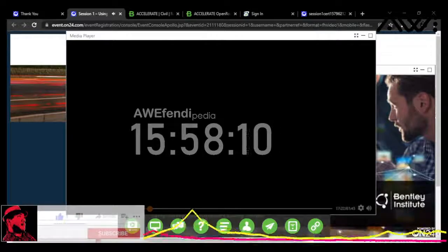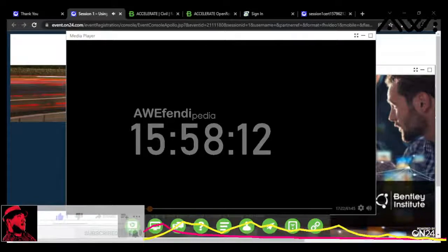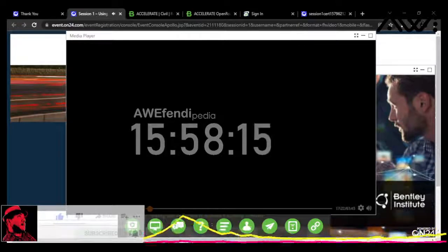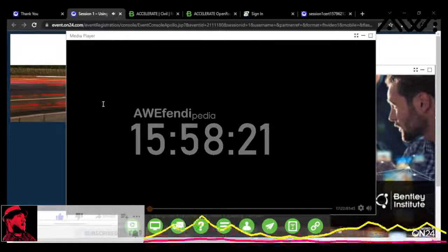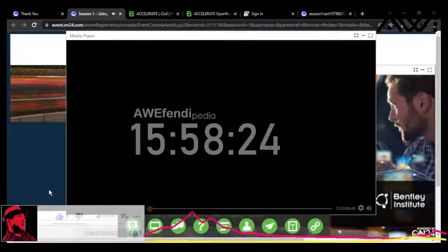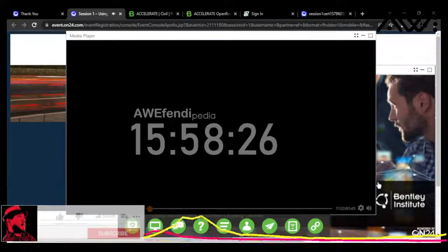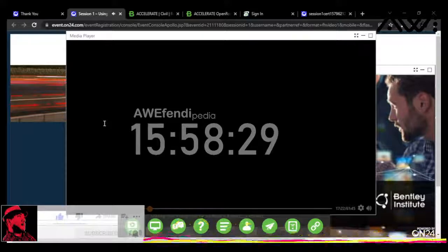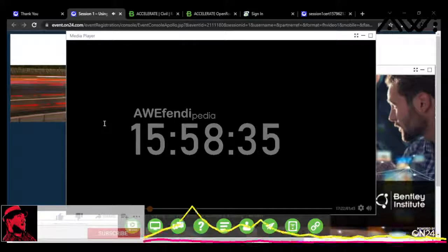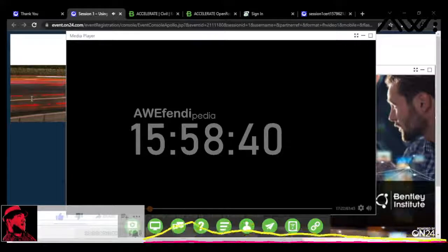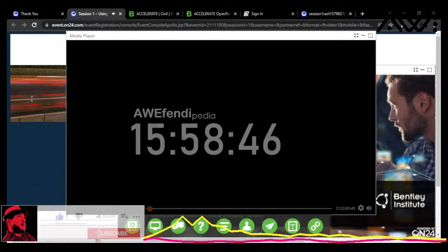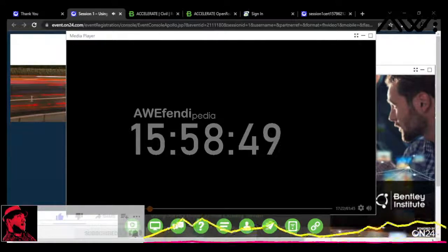And then primarily in this survey workflow, I'm going to be working here in the Analyze tab. And we'll be using details a lot. We'll use some of these other tools as well. So that's survey workflow up here. We're probably going to be on the Analyze tab. And you'll notice that I've already looked in the Explorer dialog. Without explaining how I got that up, most of these tabs have the Explorer. If I go to Home, the Explorer's here. Field Book, the Explorer's here. So if you don't have your Explorer already loaded up, I'm going to be using that a lot today to look at our feature definitions and our settings. Okay, so hopefully all of our interfaces look the same now and we can continue on.